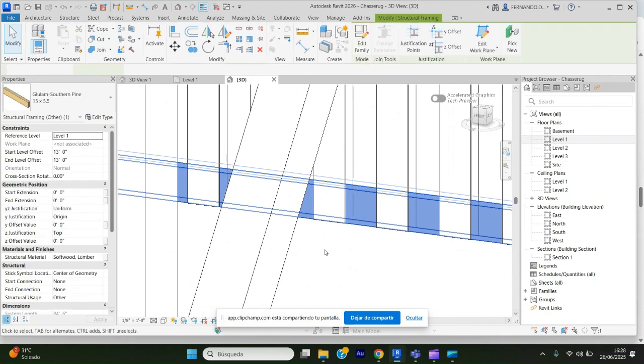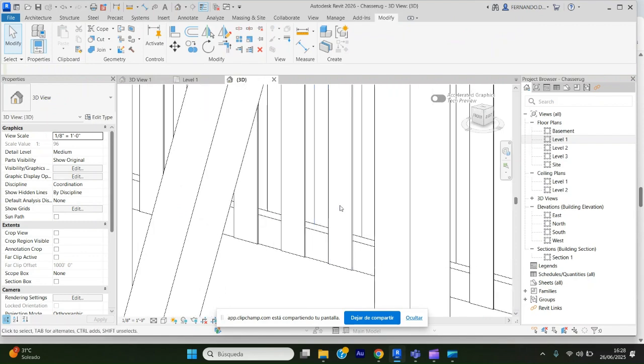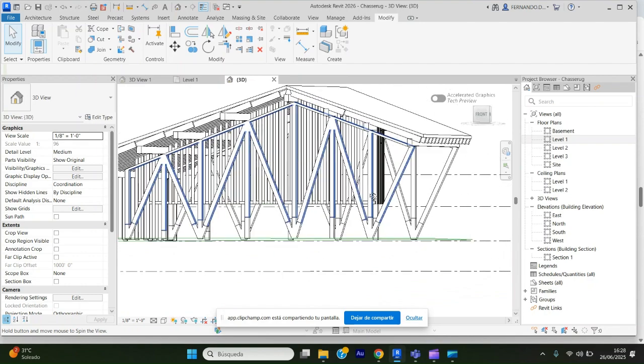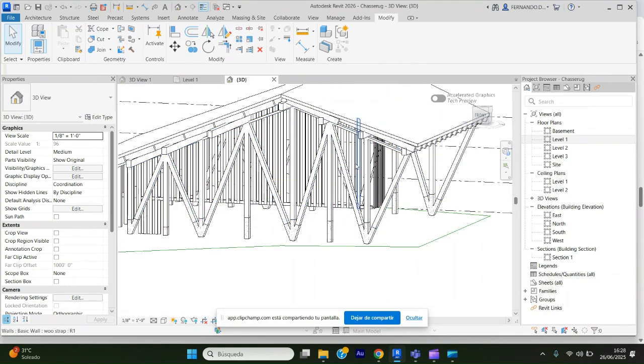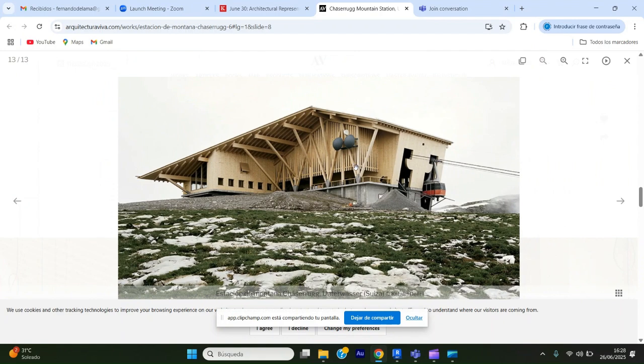Okay, so this beam is nailed to that structural element, to the truss, and then all these straps are nailed here to that beam. And there, we should have something similar probably at this level. I don't know if we can tell. Right. We can tell that there's a structural element here. You see that horizontal line, and probably there is another one over there. I can't tell, but yeah. Or maybe the other horizontal element is there at the top.